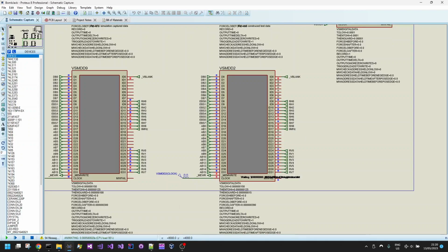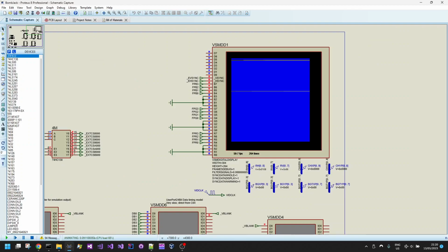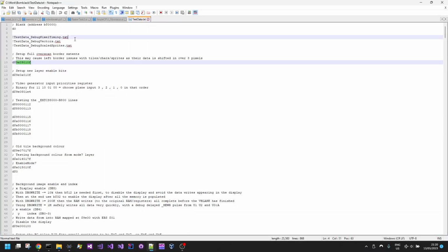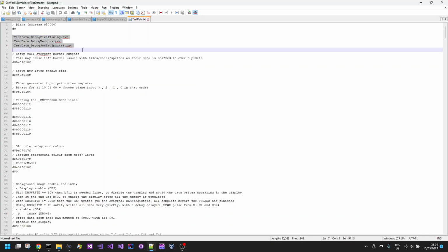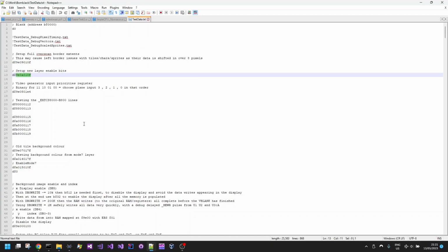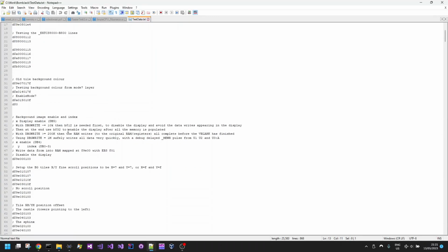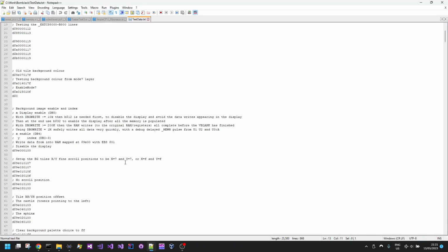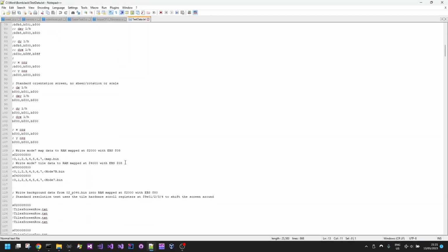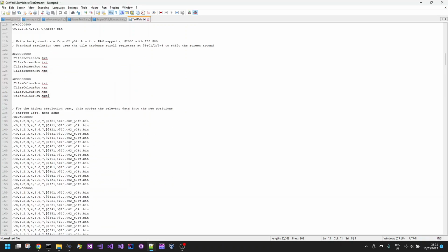And then it will output the signals to the video hardware, and this can add values or write values into RAMs. It can update the palette entries, for example, and then the video hardware will actually render. So this input test data file here can include other files, or it can output data directly, and we can recursively construct quite complex test data that I want to test.